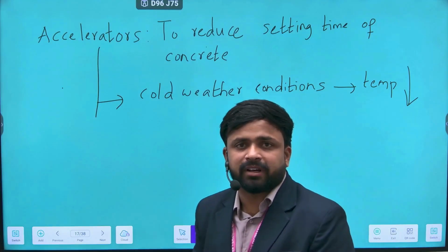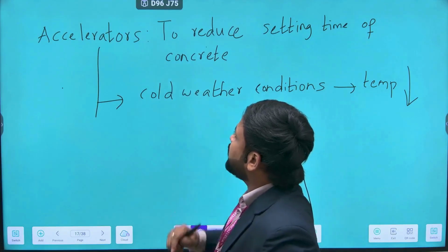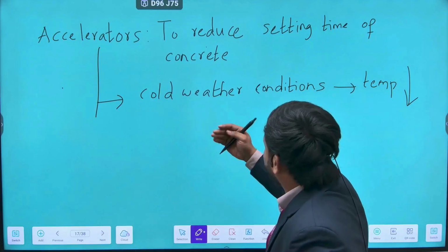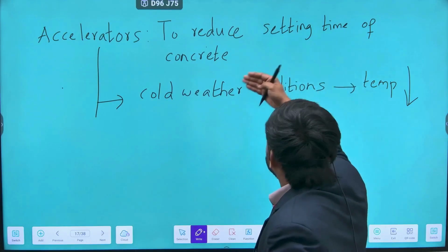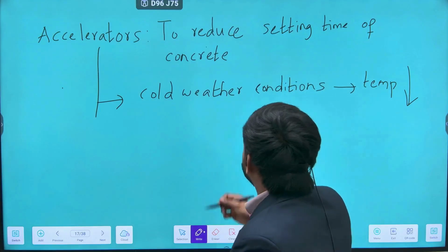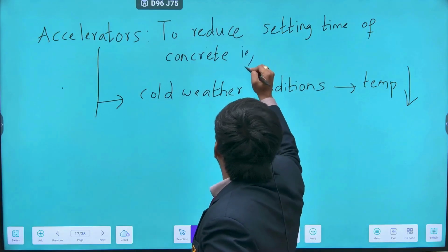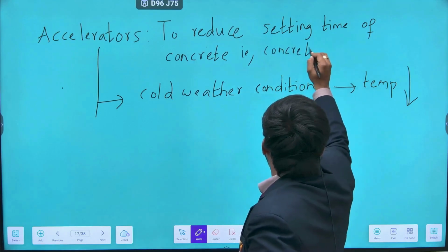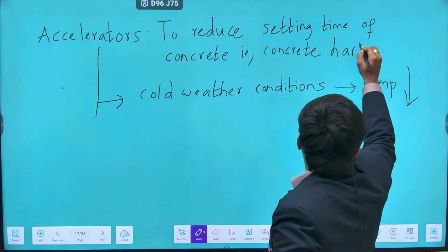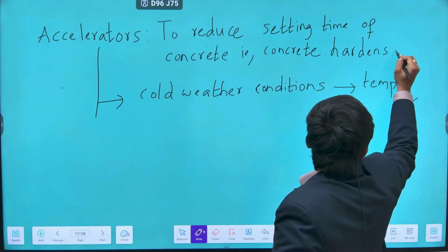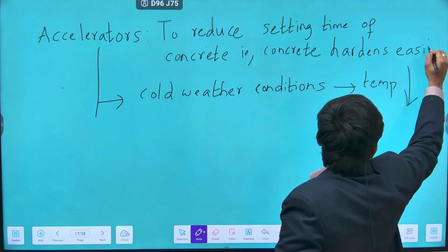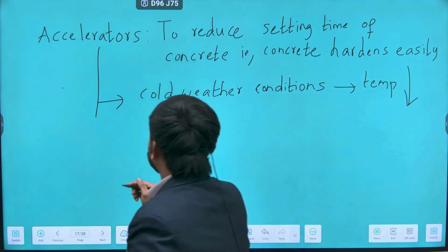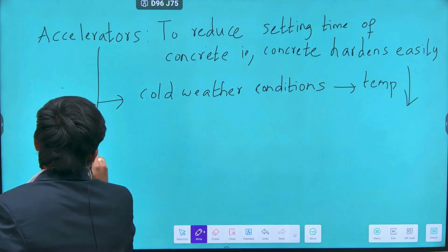I have only a limited time, so I'm going to add the accelerators. It helps me to reduce the setting time of concrete there. That is, concrete hardens easily.